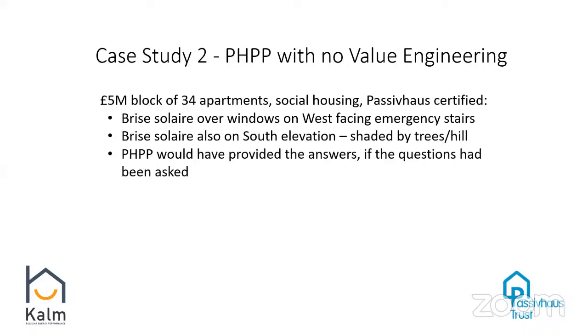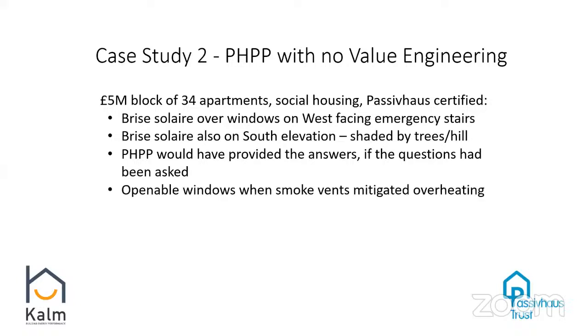Now, PHPP, if it had been asked the right questions, would have told you the answers: yes, you don't need brise solaire if you just do certain things. Openable windows on the stairwells weren't needed for mitigating overheating, because the smoke vents at the top of the stairwells were linked to thermostats, so they opened to mitigate overheating. So that was already taken care of.